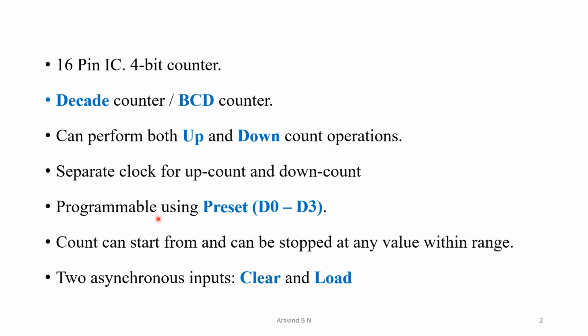It is programmable in the sense that by using the preset operation, the counting can be started from any value within the range. In order to set this preset value, we have separate input data pins D0 to D3. It also has two asynchronous inputs, that is clear as well as the load signals.